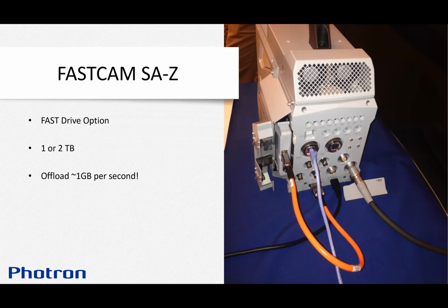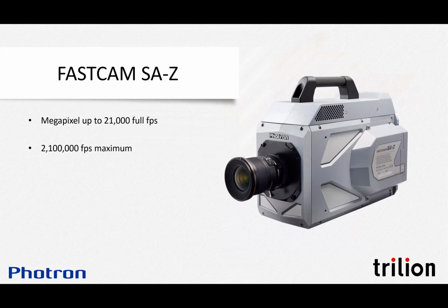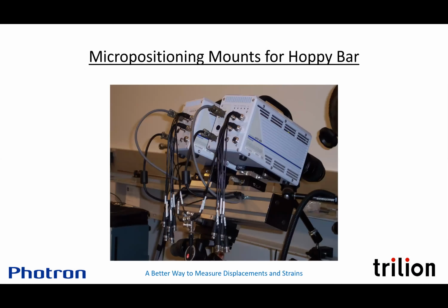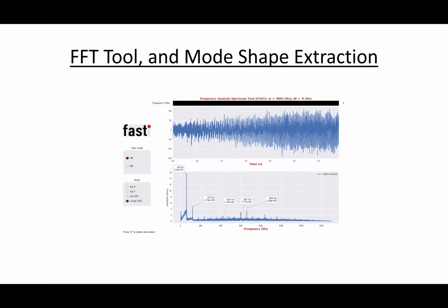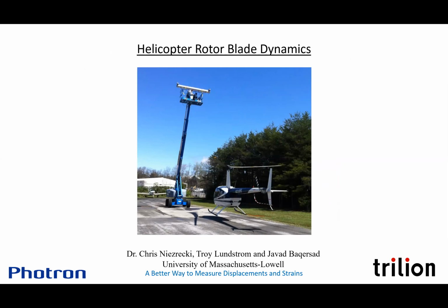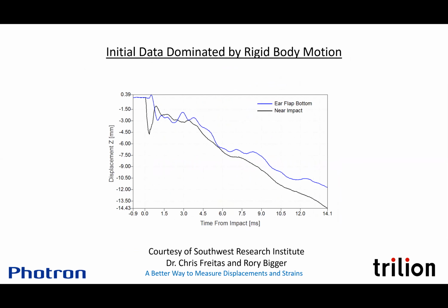So what can go wrong with that? There's an assumption that among the points you pick there's no deformation. In the training, I have some visuals I go through. If you pick deforming points, then the best fit plane would itself be tilting, and it would be adding nonsense displacements rather than correcting them.